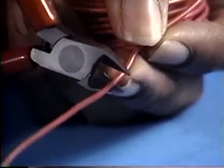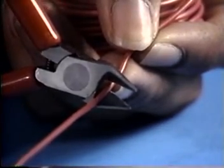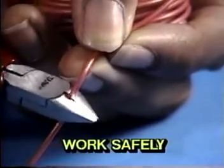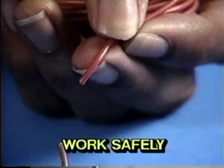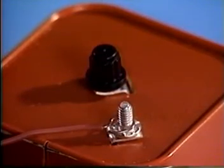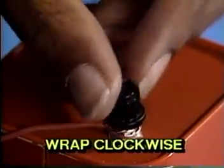Number 2. When cutting wire, always point the beveled side of the cutters down toward the floor. Cutting wire can shoot several feet and injure someone. Always work safely. Number 3. When attaching a wire to a binding post, always wrap the wire in a clockwise direction.